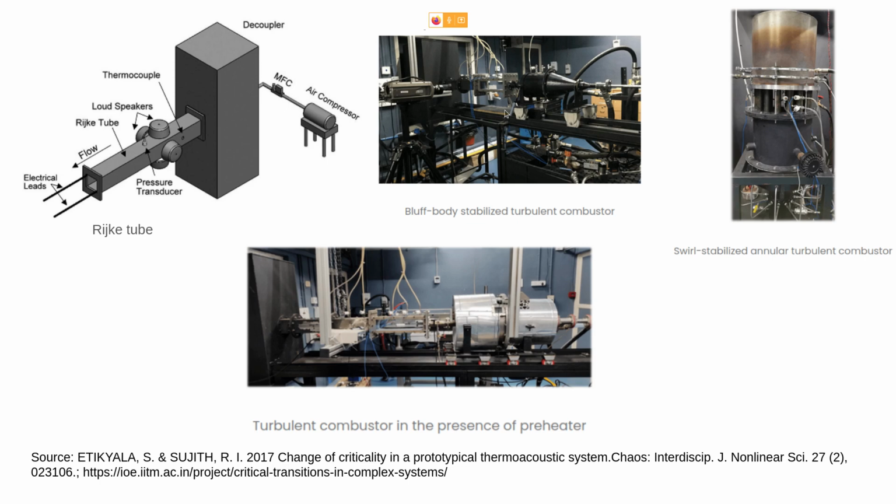In combustors you need to hold the flame properly, else you would need to reignite the fuel and air as they keep coming in back to back. So you need certain flame stabilizers, and we use different stabilizers. We use bluff body stabilized combustion, and we also have a swirl stabilized combustor. Here we use a bluff body stabilized combustor, and you have the fuel valve provided here, and air coming through; they come mixed together into this plenum chamber, and pass through this tube into the combustion chamber.